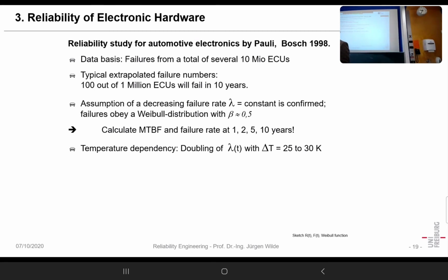If temperature alone is doing that, then it's true, but you also must keep in mind that in real automotive applications, we have many failure causes, and also many stimuli which lead to degradation, and in that way, for instance, vibration also. Temperature is not the only effect we have here. But that again was, you could say, hard data from the field.